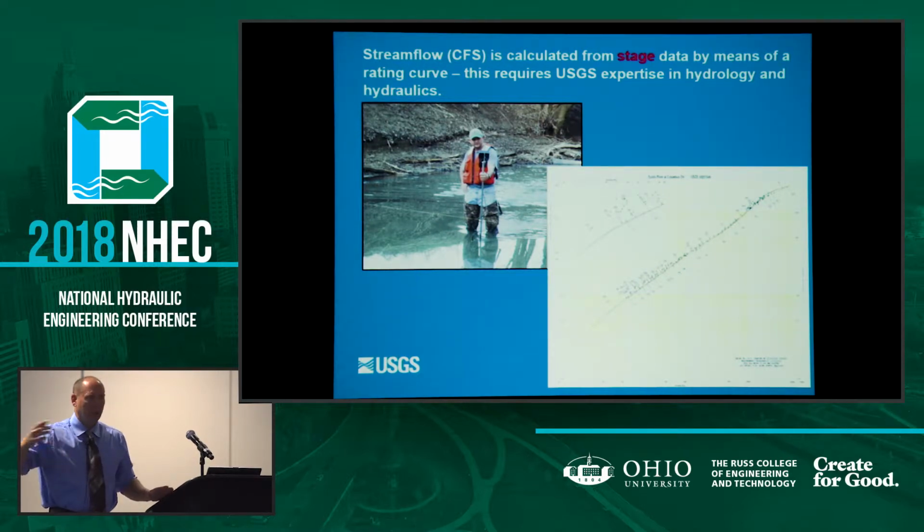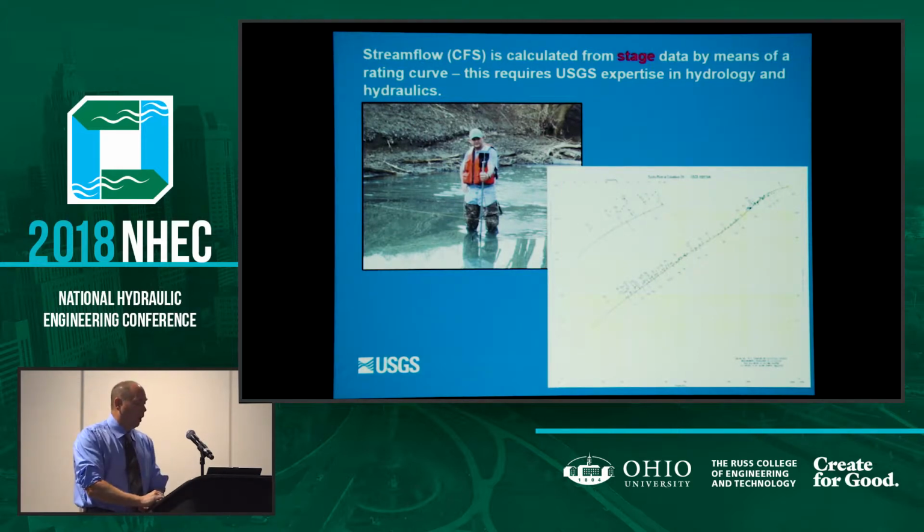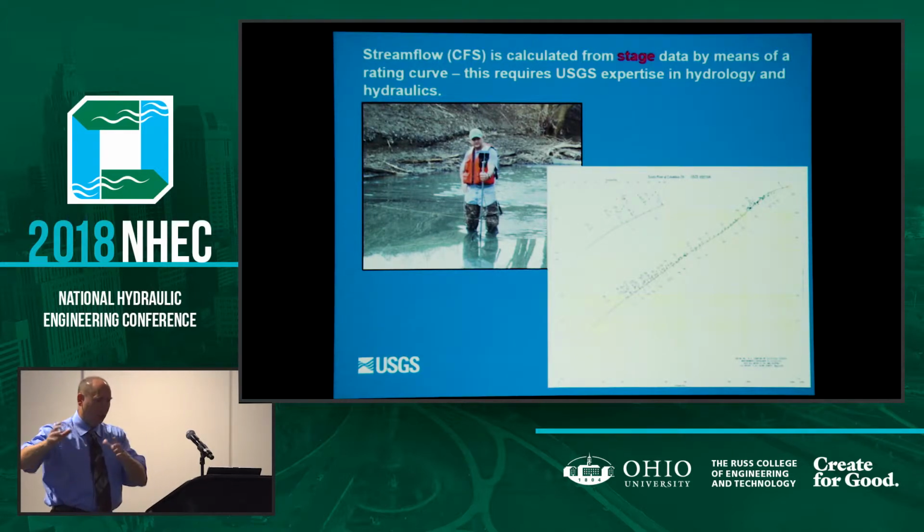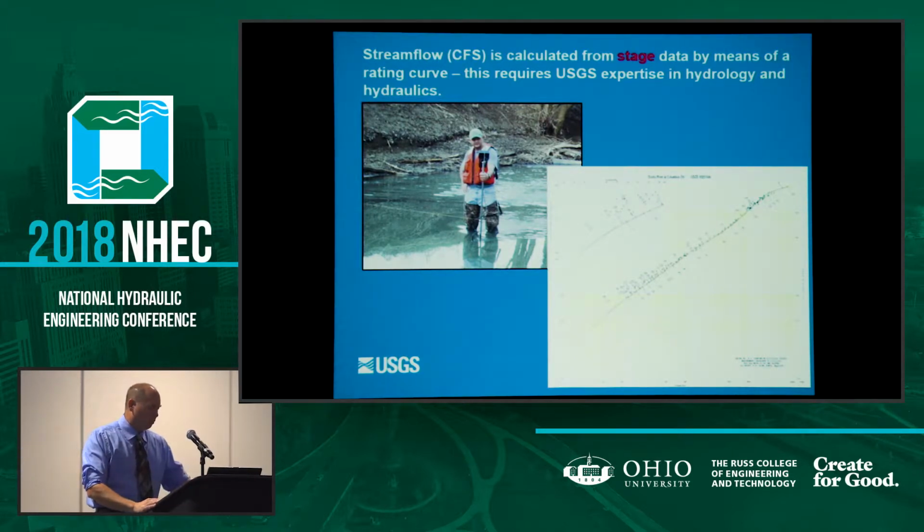On the other hand, and I saw this a lot in Missouri with a lot of sand channel streams, there's a lot of degradation issues, especially along the Missouri River. And the Missouri River is actually, the bed is degrading. So for a given flow, you'll actually have less and less stage. So yes, the rating curves do change over time. Nothing's stagnant in the water business, as we all know. And we do our best to capture that stage discharge relationship given the conditions that are presented upon us.